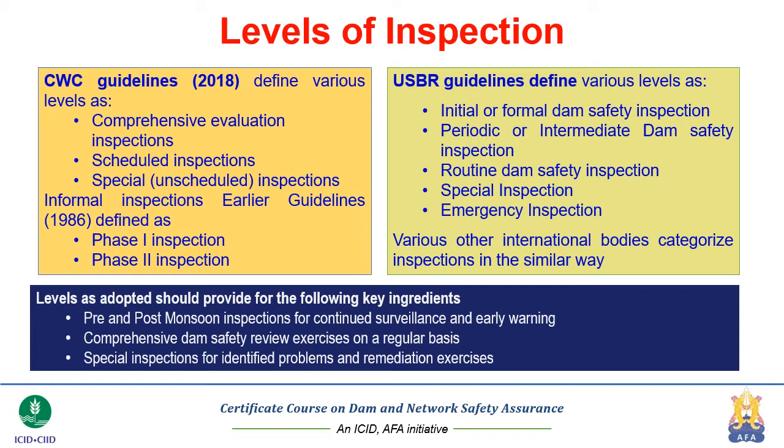Scheduled inspections are most frequent, where every monsoon, every pre and post monsoon period, you have to inspect the dam by a generally competent engineer who has some familiarity with the dam and provide indicators about the performance of the dam. With that, there may be need for escalation, or if there is no need for escalation, then every longer